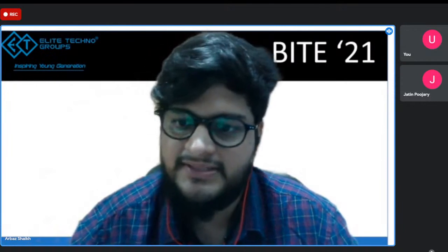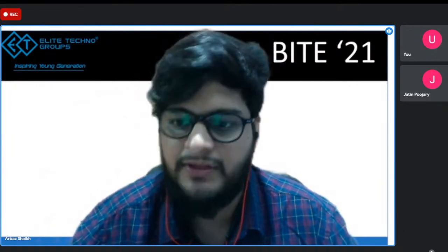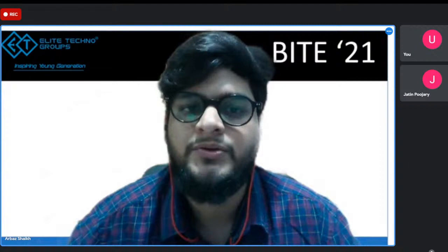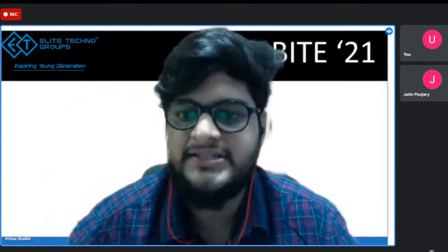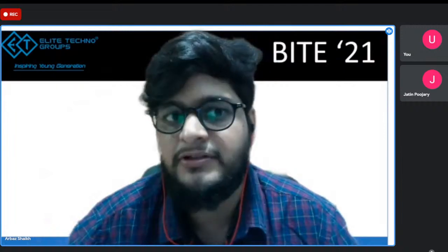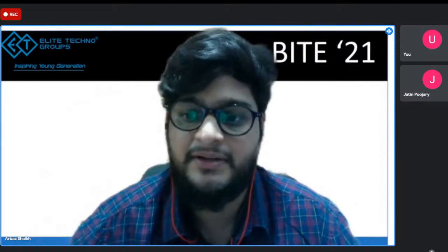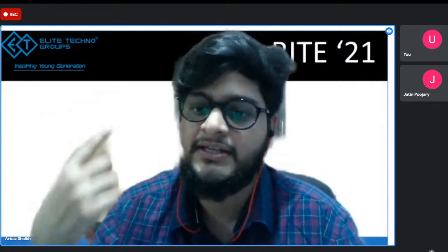Okay, Raja is asking how to calculate the slip angle. We don't have any explicit formula, only with some software. Okay, it is not completely like that. Not just by software. You can calculate it theoretically, but it's a very tedious process. You need to do your integration, derivation, and all those things. But it's better to have an experimental approach to it. What companies do when they manufacture a tire, they do experimental tests on the tire. They plot out graphs, and based on those graphs, they create software which will essentially give out the data you need.